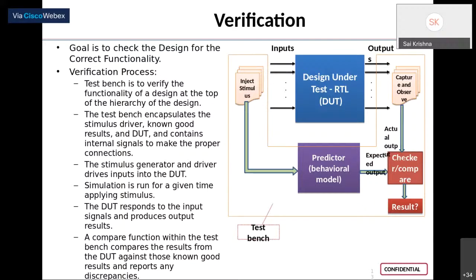So that is why your functional verification is very important. If your functionality itself is not proper, then it makes no sense to go ahead, convert it into a gate level circuit in synthesis, and then perform physical implementation.